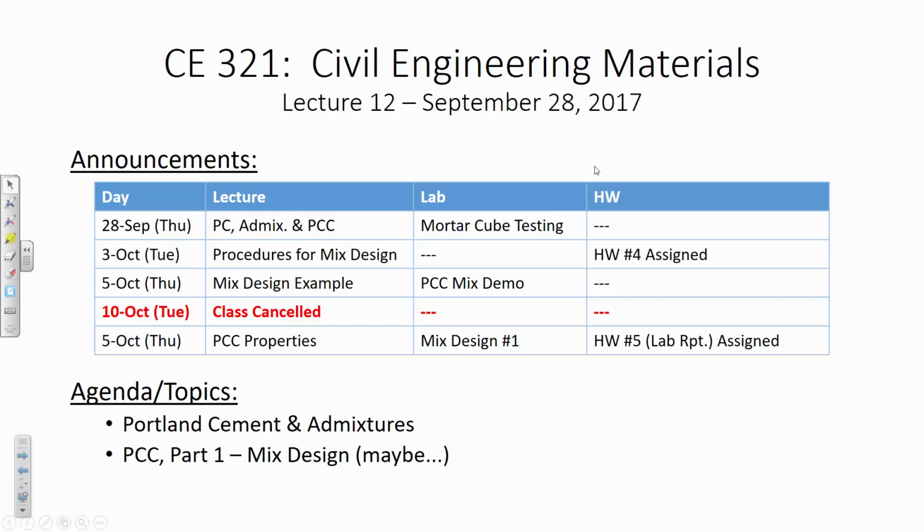Now today, we're going to be busting mortar cubes in the lab. That'll be pretty straightforward. You all cast the cubes. We're just going to test them. Depending on time, I know I want to test at least 1 from each group, and depending on how the results are, we might test 2 from each group. We're probably not going to test all 3 from each group. So we're only going to do a 7-day test for the cubes. We could do more, but we're going to be busting cylinders for the rest of the semester. So, you know, once you've seen it once, it'll be fine.